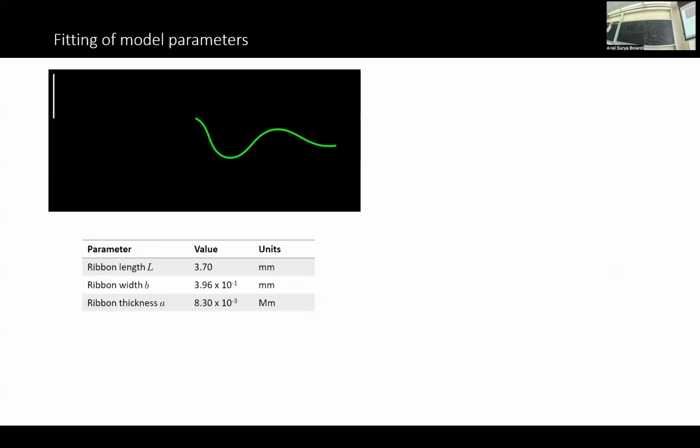We can cast these components, and by running finite element simulations, we can see that for some choices of the parameters, nothing happens, and for other choices, something happens, the filament swings. But we would like to compare these results with the physical experiments, and for this we need to appropriately choose the parameters. The geometric measures of the ribbons are measured, while there are three parameters that are very difficult or impossible to measure from experiment.